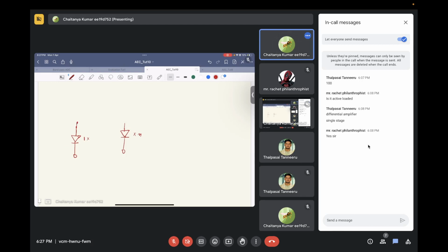What we want is this 1x diode voltage, which varies with about minus 2 millivolt per Kelvin, like a slope, and we want to compensate it. So we make sure that these two voltages are equal.